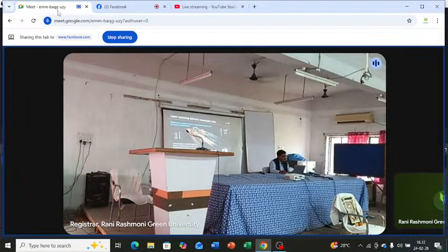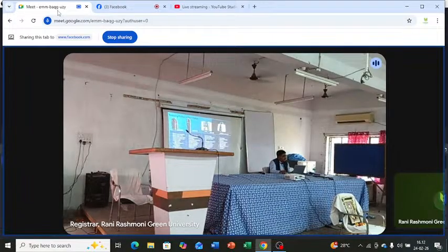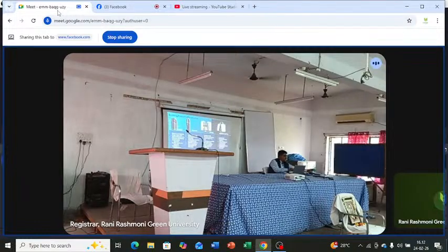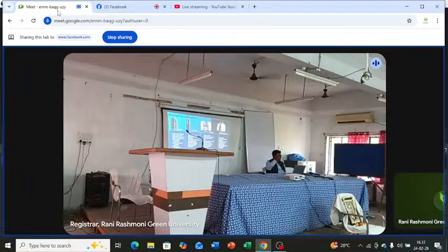So which are the instruments that it is capable of? These are the instruments. Very small but handy. These are useful. Okay, a little more in detail. The BLK 360, this is very small, just the size of this module, and it has only one button. Just press it on, put it on a tripod to scan the entire area around it. And it will make all the images and the data that we get will have coordinates.